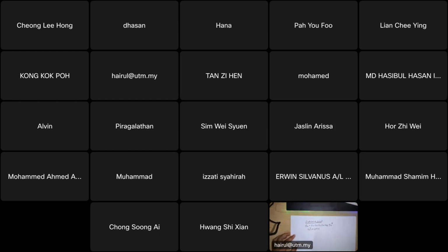Surface factor depends on whether it is ground, machined or polished. Temperature factor depends on the temperature condition of the shaft you analyze when it is running. And the reliability factor is for 99%. These are all the modification factors, so we get our Sn in megapascal.